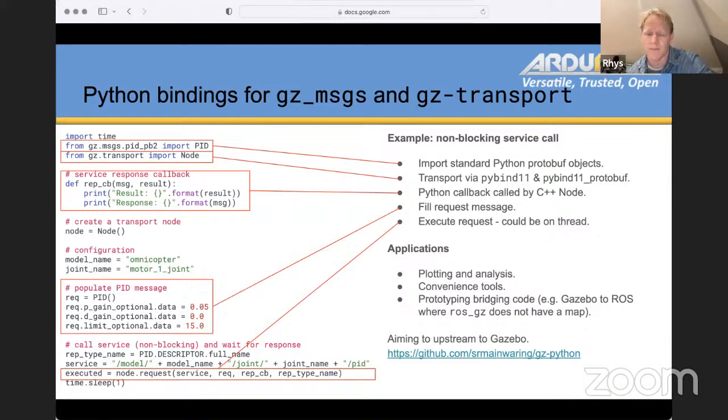Where it's handy is there is a bridge. So the ROS GZ bridge does do a similar thing. It's a series of C++ libraries. However, if you wish to get a new type of data shipped into ROS, you need to modify that library and provide the mappings for that. And there are many things. The set of things that you might be interested in querying in the simulation directly is much larger than the set of standard messages that you'd put through onto a ROS bus.